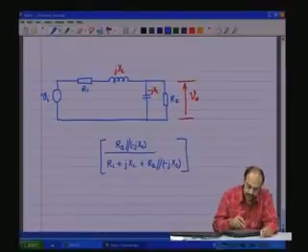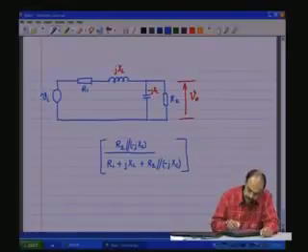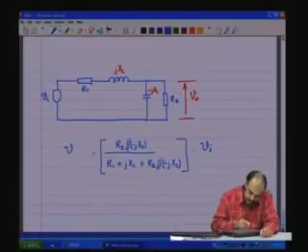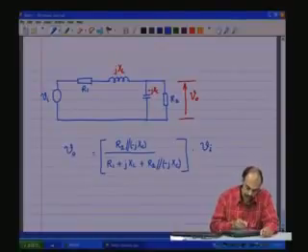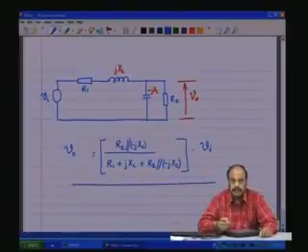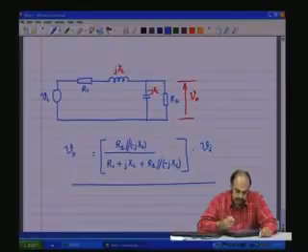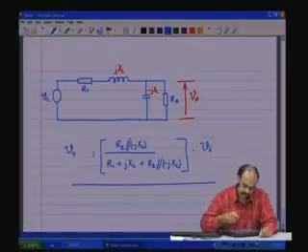This is the attenuation factor. This impedance divided by all the impedances taken in series is going to be the attenuation factor, and attenuation factor into Vi will be your V naught. So, this is the input output relationship for sinusoidal excitation Vi at the frequency omega, at a single frequency omega, given as such under the steady state conditions.